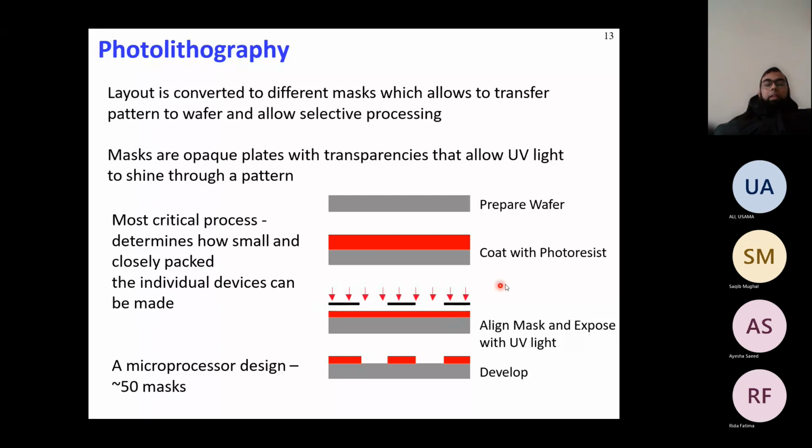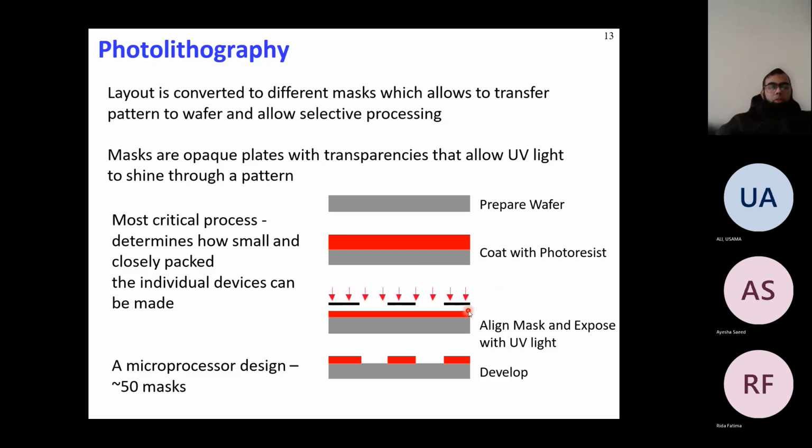This mask is the design provided by the designers, Qualcomm, Nvidia, etc. In present day technology, there will be multiple mask processes. You cannot achieve it in a single mask process. So whenever you need to pattern, meaning you need to mask some area, you do photolithography, you deposit resist, you expose it, and if it is a positive photoresist, the resist gets weakened, and you develop it in some developer, and the resist gets removed from the area which is exposed.